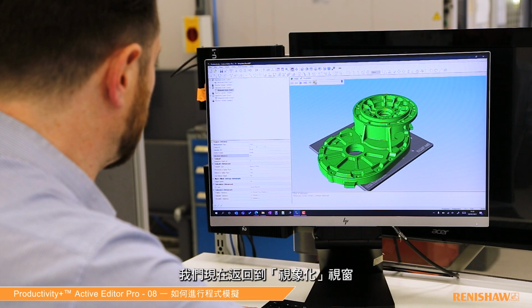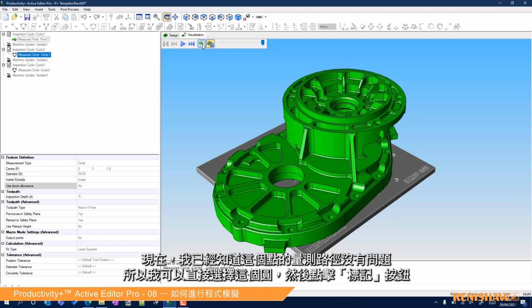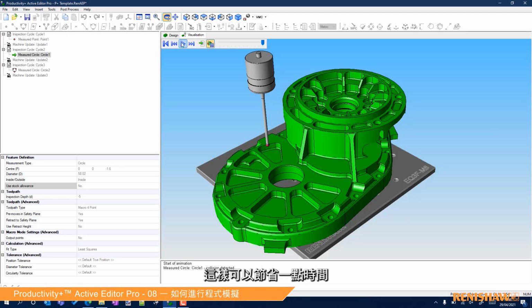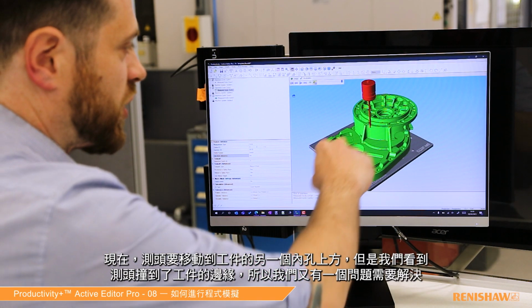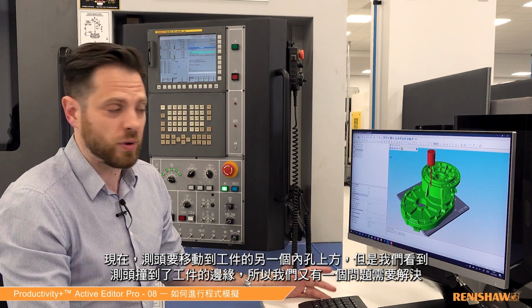So we'll go back to visualization. Now I know that point was fine, so I might want to select the circle and use my marker. So you can see the probe's now jumped to that point in the program, so we're just going to run it from there, just to save a bit of time. So I'm now going to hit play. And sure enough, it measures that feature absolutely fine. Okay, so now it's going to move across to our other bore, and actually, as you can see there, that's now collided with the edge of the part. So we've got another problem to address here.